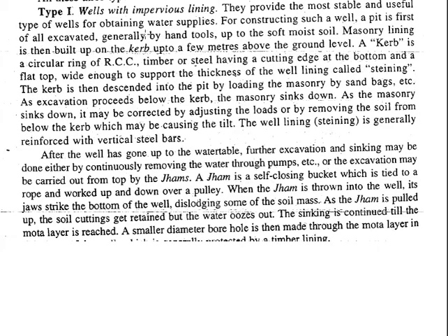So if you are constructing the well with the impervious lining, the edges of the wells are constructed using stone or brick masonry, and we mix them with the mortar layer, so that the water from the sides of the well does not enter through it.